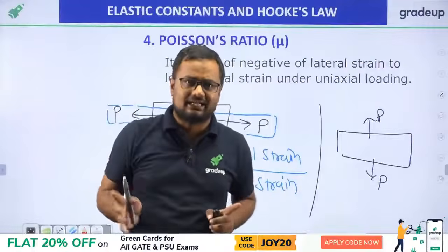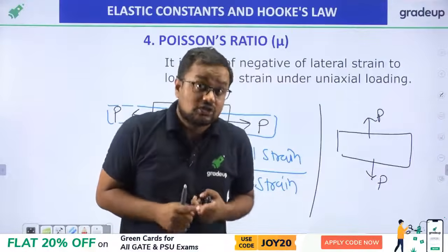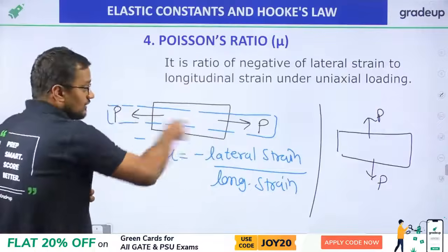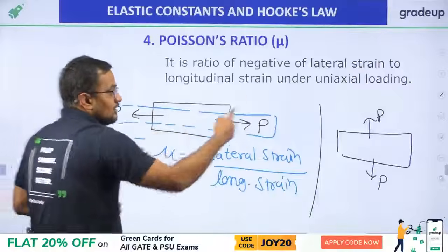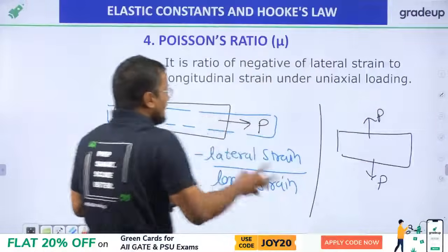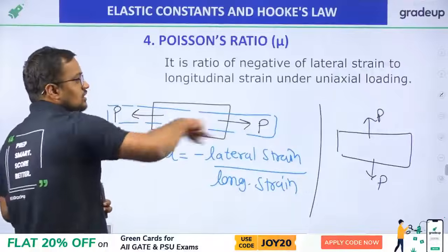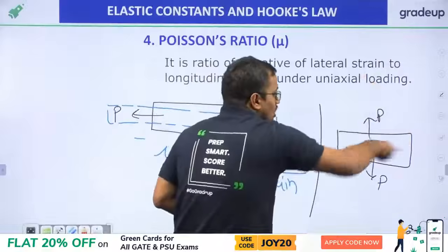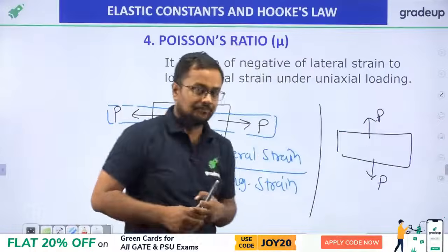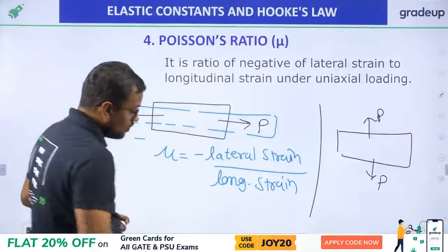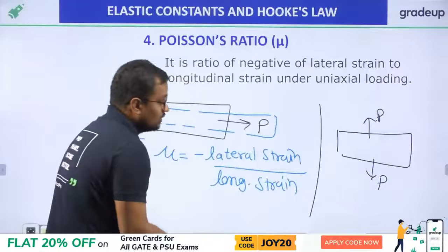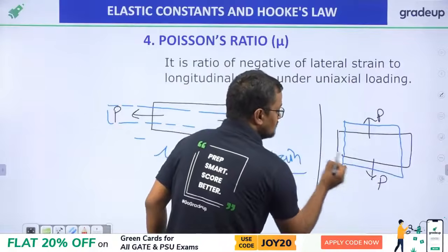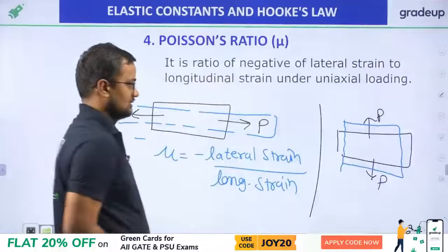That is totally incorrect, my friends. The axis where the load or stress is acting is the longitudinal axis. If the load is acting like this, this is longitudinal, and all others will be lateral. If this is longitudinal, all 90-degree axes to it will be lateral. Of course, with this kind of force, it will elongate here, but it will contract like this. The shape, my friends, will be like this.